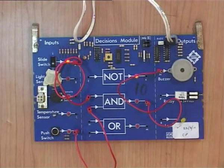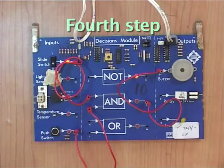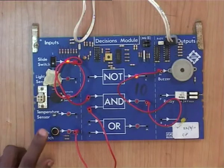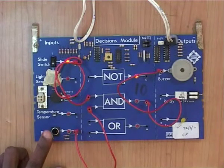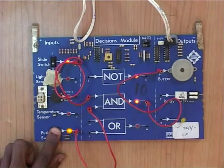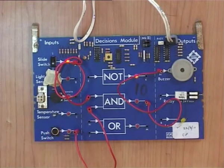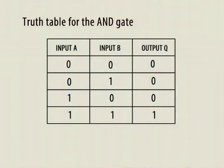The fourth step, the slide switch was at position 1, which is high, and then the push switch was pressed so that its input is also high. And in that case, the buzzer sounds. We can represent this also on a truth table as shown on your screen. So that gives us the complete truth table for the AND gate.